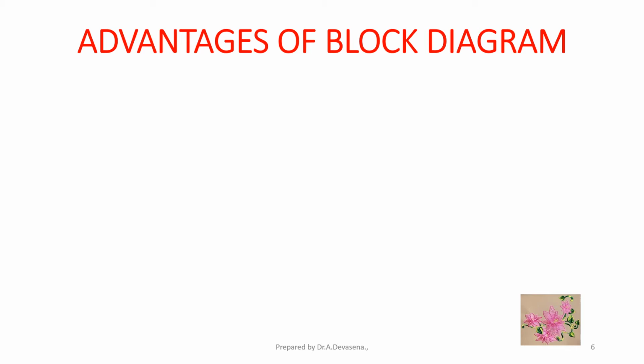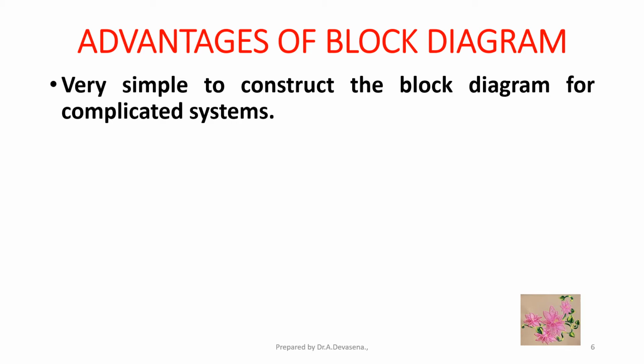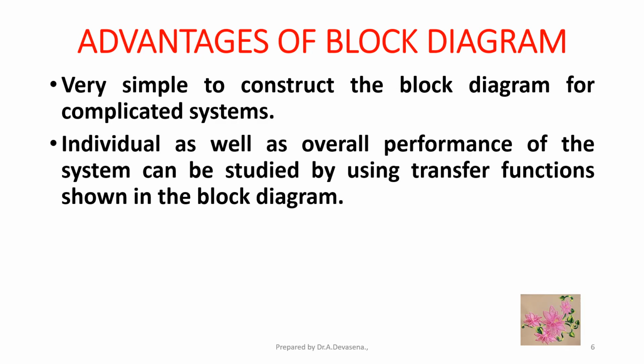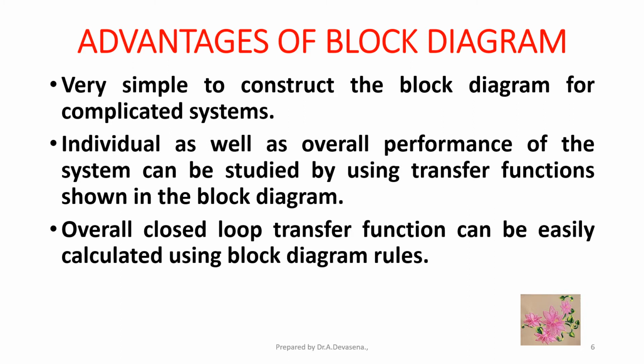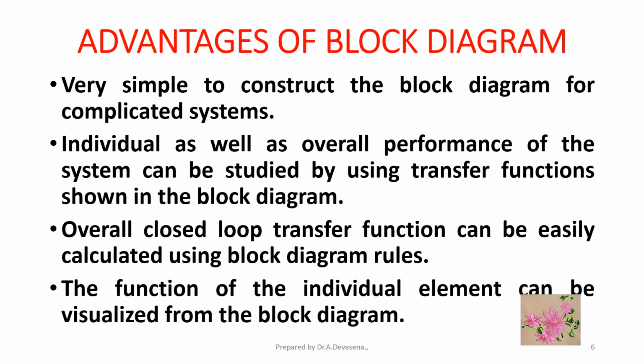Advantages of block diagram. It is very simple to construct the block diagram for complicated systems. Individual as well as overall performance of the system can be studied by using the transfer functions shown in the block diagram. Overall closed loop transfer function can be easily calculated using block diagram rules. The function of the individual element can be visualized from the block diagram.